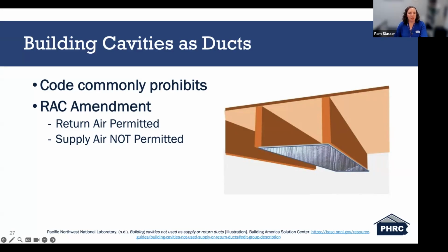The image on the slide illustrates how a cavity might be used as a return pathway, but it's important that it is done carefully and in accordance with the code requirements. And just remember, return air is permitted, but supply is not.